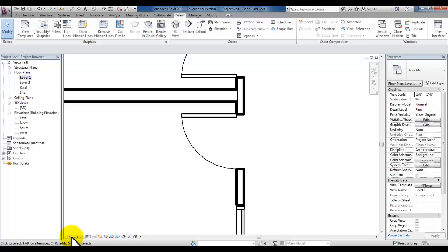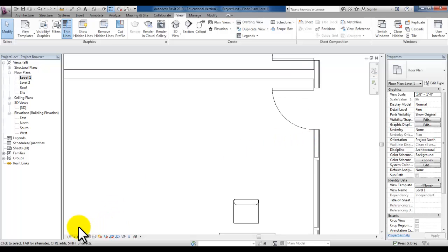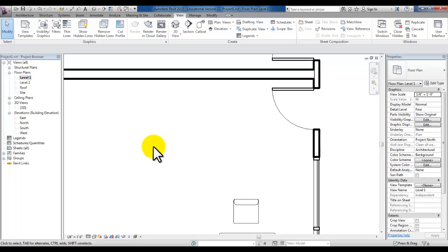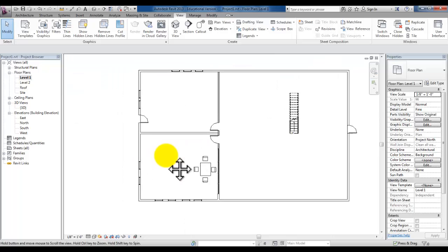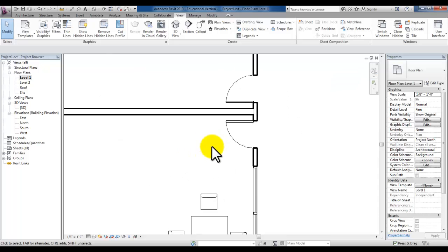they're walls, and we're at 1/8 of an inch, which we'll change a little bit later, we can go to the View tab here at the top and pick Thin Lines so that you can see a little more detail to your drawing as we're close in view to an 1/8 inch scale. Notice when I have thin lines off and I zoom back, at an 1/8 inch it looks good. So it has to do with the zooming level and what scale you're plotting.